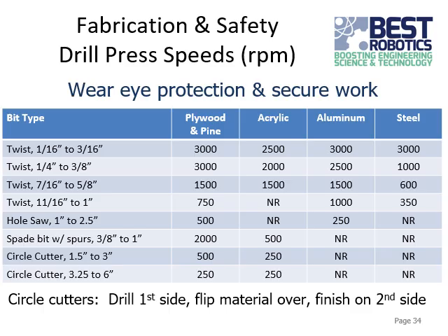And then for drill presses, I've added this table here. This is just for reference, but you can find this online. A lot of drill presses, at least that I've seen, will have a little table like this for reference, either taped inside the cover of it or something like that, so that you always know how to use it. But in general, with smaller things and smaller drill bits, you can go faster. With bigger ones and hole saws, you need to go a lot slower.